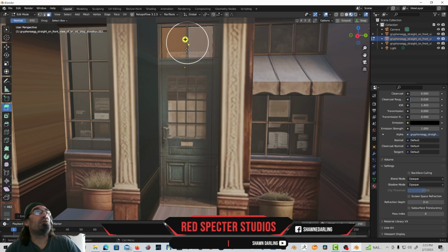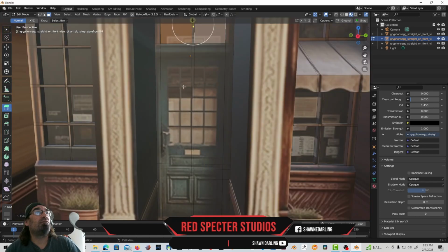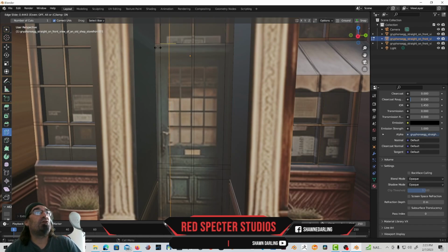And now if you wanted to separate those out, you could. Also, you could separate the door as its own piece, but it's not necessary. It's just going to minimize your polygon count if you need to, or keep the busyness of all the edges and lines down, which can definitely be an issue depending upon what you're trying to achieve. You might want to keep that polygon count much lower, or your scene way less busy, just so you can see what you're doing.